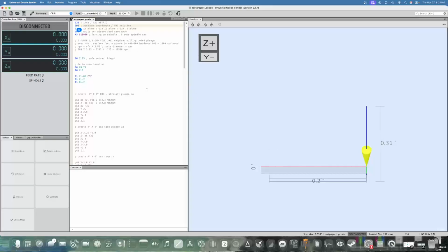What that does, I made a quick example here, and right here I got Z1 going down 60 thousandths into the material, and then I got G1 coming over, or G1, I got X coming over 0.200 thousandths. And you can see right underneath that, I'm telling it to G1 X minus 0.200 thousandths again, but you see in this illustration, it moved over 200 thousandths and stopped because I'm in absolute mode and it can't move to 200 because it's already there. It got put in there twice.